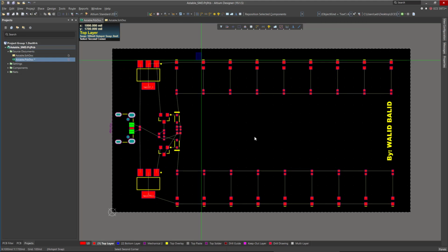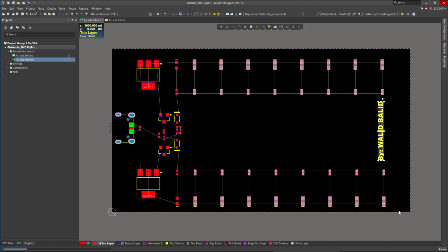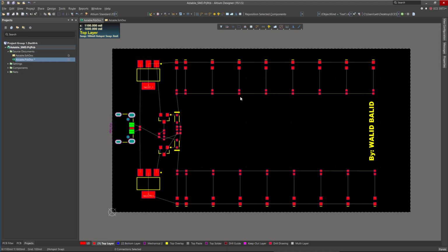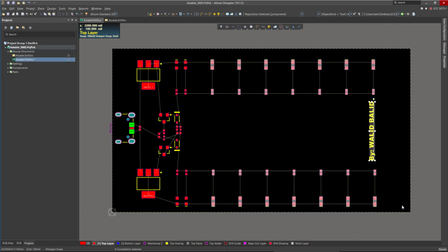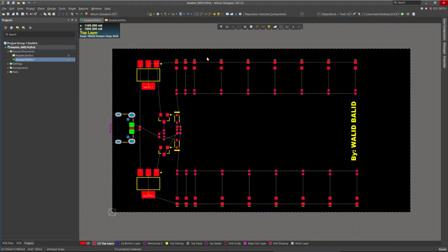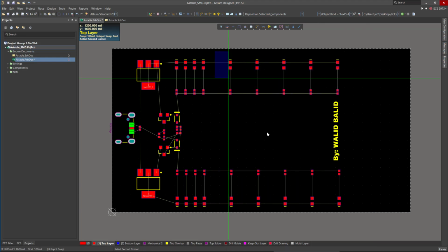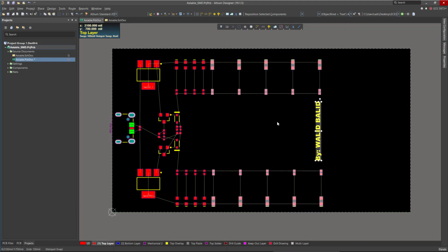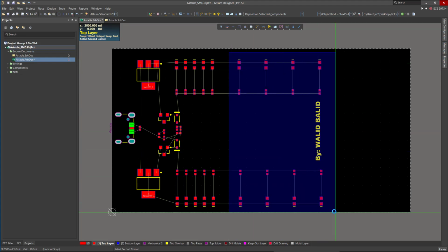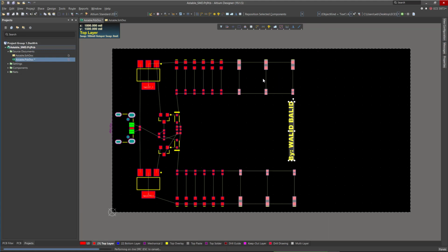So now at 100 mil, select all these. If you click on Control and left arrow on your keyboard, you see they are moving. So it's 2 steps. This is the fastest way to keep them aligned. 1, 2, and select these. 1, 2. It's just that you are holding Control down. Now you don't have to hold Control down. Now you hold Control down and the left arrow. Then release the control, select the component, Control down, and they will be aligned. One more.